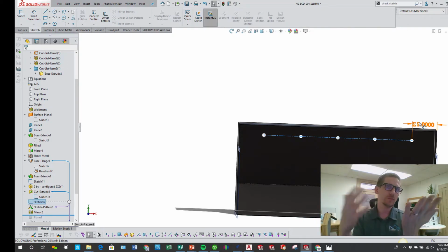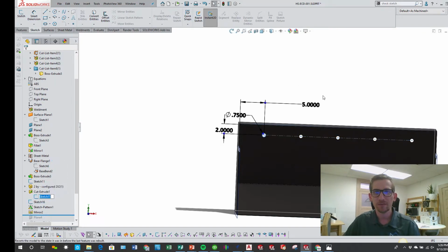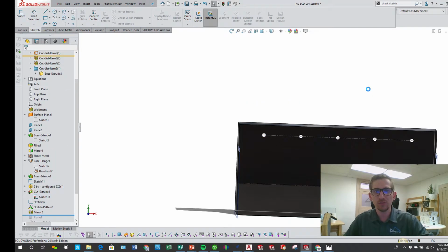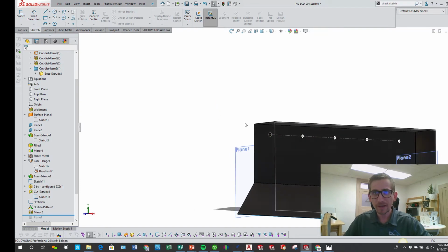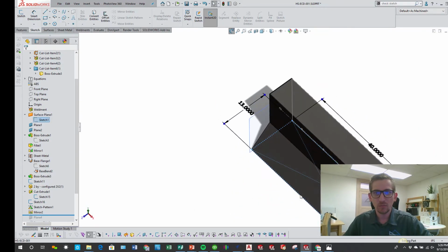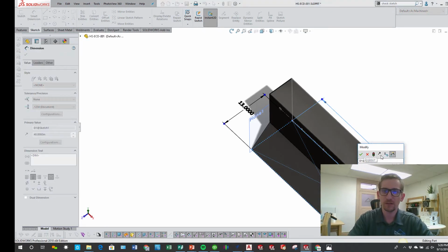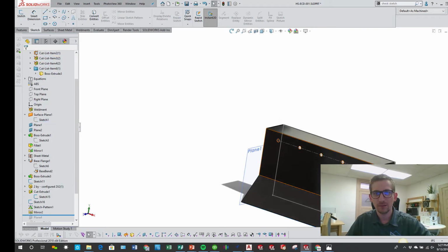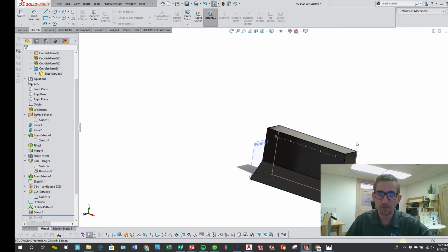So I wanted these holes to be centered about my display. So I'll simply come back to sketch 15 and we'll say, let's make this go back to 4, do a Control Q. Everything gets spaced out properly. Now, once again, I came in here and I updated sketch 1 to being 40 inches. So let's go back to 34, and I'll do a Control Q again. You'll see everything got resized for that 34 dimension.